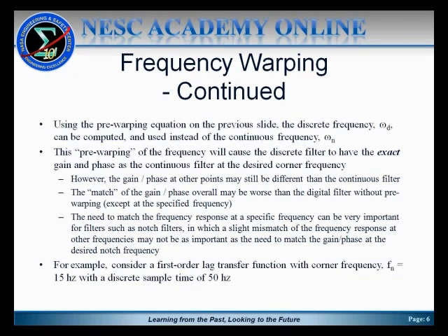So why would you do that? Go to the trouble of pre-warping your filter coefficients. The reason is if you had a filter that has to be defined at a specific frequency, like say a notch filter, where if you have any mismatch of the frequency response, you might not actually cut out the frequencies that you're intending to. So in that case, you might want to pre-warp your filter to line up the magnitude or the attenuation of the filter and the phase at the proper frequencies.